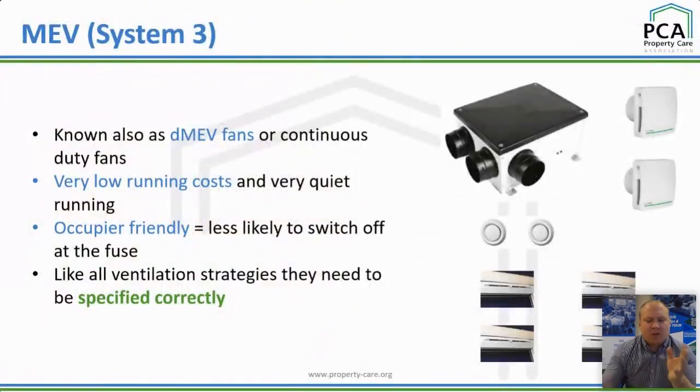System 3, I sort of alluded that people are moving more to system 3 now. The reasons being they are continuously running, so they're always dealing with the issue rather than just a form of purge ventilation, which is when the issue reaches a peak, as it were. Because they're constantly dealing with the issue, they tend not to be as noisy. They're more occupier friendly as well, because they're not turning them off and things like that. So there tends to be more of a move to this as well.